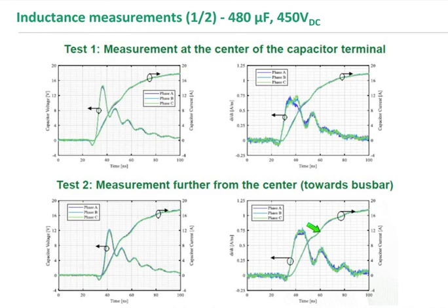Actually, these measurements which you can see here are done with a single pulse. So actually, we are charging the whole cap link system and then we are quickly discharging it, making some kind of a short connection. And then we are measuring here the overshoot voltage. This is what you can see here. This is the overshoot voltage. This is quite important to calculate the inductance. As you can see here, it's in the range of, let's say, 14 to 15 volts.